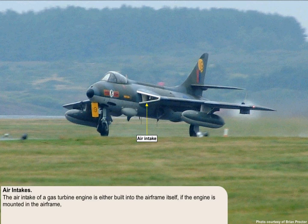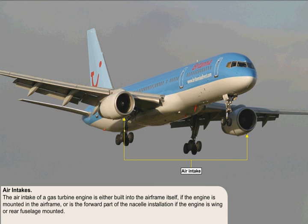The air intake of a gas turbine engine is either built into the airframe itself, if the engine is mounted in the airframe, or is the forward part of the nacelle installation if the engine is wing or rear fuselage mounted.